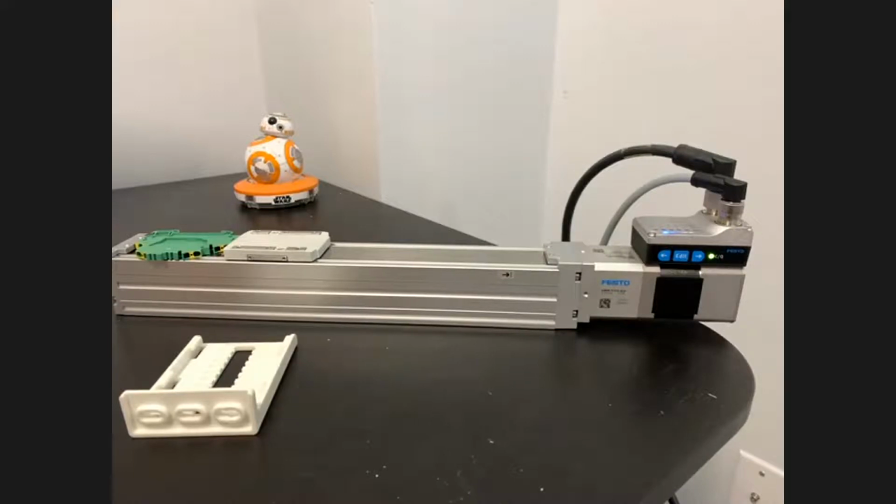Kevin, I think this is a really nice feature, being able to approach quickly and then slow down. Typically, when you want a repeatable measurement, what's key is a repeatable force. Low force is preferred so you deform the part less. But in pneumatics, if you're adjusting your pressure regulator to low force, you're also going to influence your speed, which may become a challenge with cycle time. So it's nice that you can speed up in the approach and then go to a low force, so you can have an accurate, more repeatable measurement. Very nice.